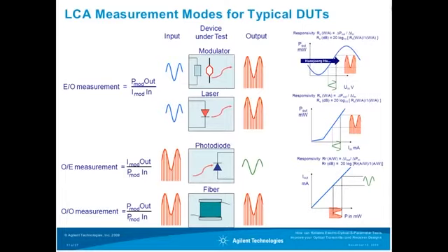the conversion is optimum if you are right at the bias point, but if you move away from the bias point, the conversion gets flatter and flatter, and therefore the conversion efficiency decreases. So it's important to set the right bias point of this component. Similarly, for a laser, you also have a bias point which is determined by the average injection current, and you modulate around this and generate, from a small signal electrical modulation, a small signal optical modulation.